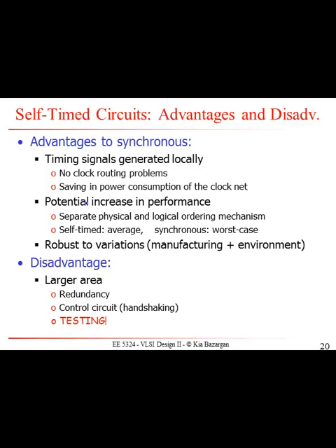So in Razor, you could potentially set your clock speed to be close to the average, maybe a bit slower, and then assume that most of the time you're going to be fine, except the cases that you're taking longer. Then Razor is going to figure out that I had a timing violation, so it's basically going to stop the system, maybe run it for another cycle, giving it 2 cycles for this operation to finish, and that way you can address the same issue.